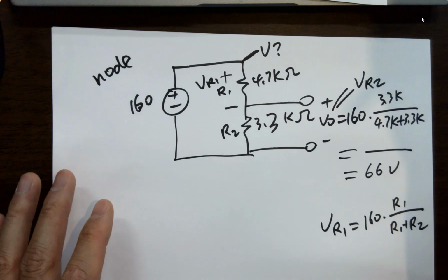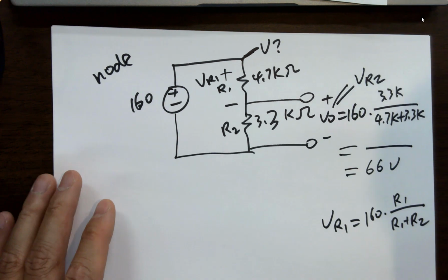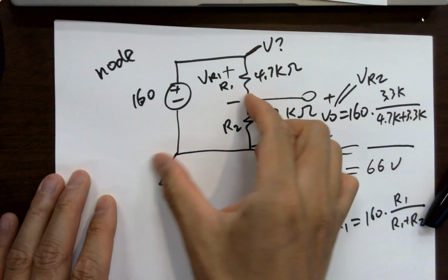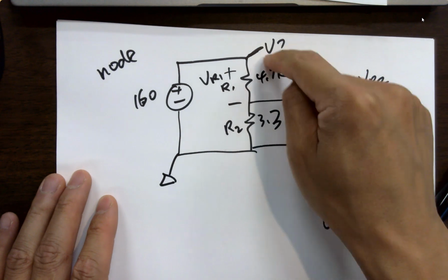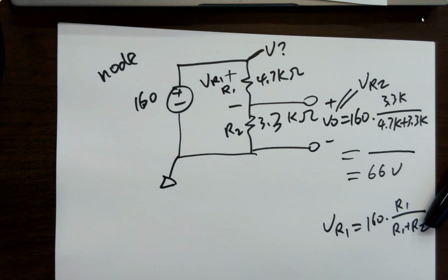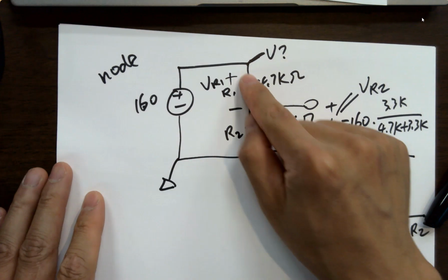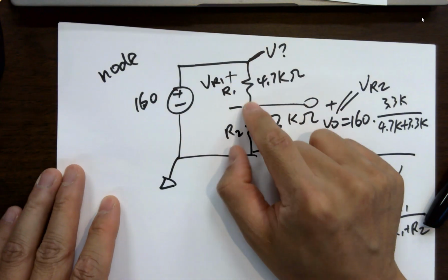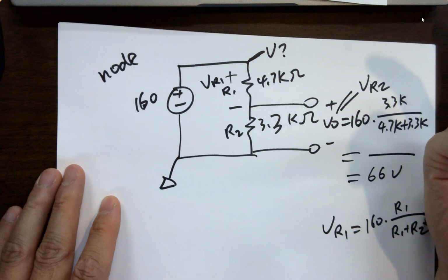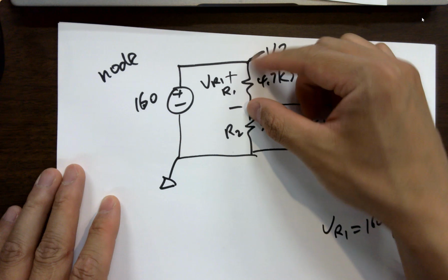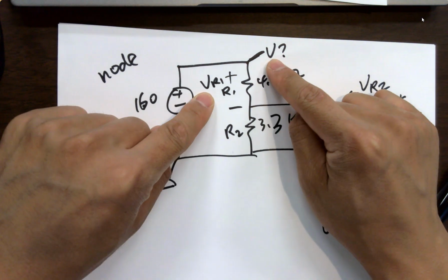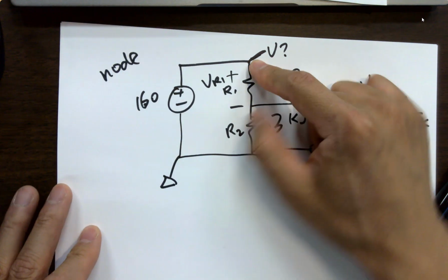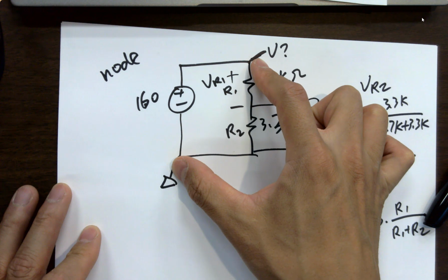The reason you can do that is because all the voltage is relative. You point to that node you are comparing to. So it's going to be this voltage minus 0, still that voltage. That's why I can directly point to it. So now I'm asking for the voltage at this node. Is that a valid question? Yes. So if I ask what's the voltage of R1, it's not a valid question, but I can ask what's the voltage drop of R1. That's valid, which is the voltage between these two nodes. So now I'm asking if VR1 equals V here, so which means VR1 is what? The voltage drop, right? And V is the node voltage, which is this drop. Are they equal? Apparently not.